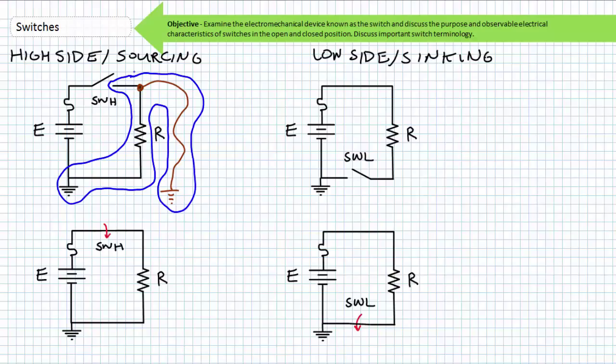However, if an operator closed the switch, the source no longer sees just the electrical load, but rather the electrical load in parallel with essentially a 0 ohm conductive path. This is a short, and a short presents no resistance to the source, and current will rise to great magnitudes. The fuse, being a circuit protection element in series with a switch and the electrical load, also experiences this same current and simply melts, becoming an open circuit through which no current can flow. In this case, all voltage would be dropped across this new open, this being the two terminals of the vaporized fuse.